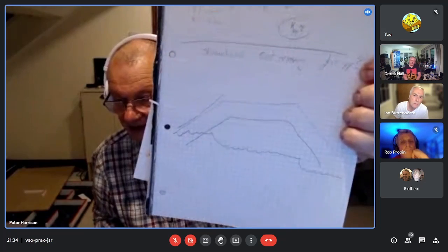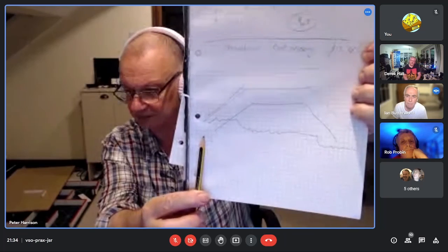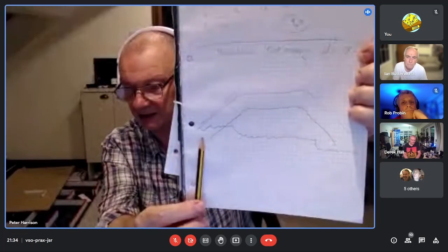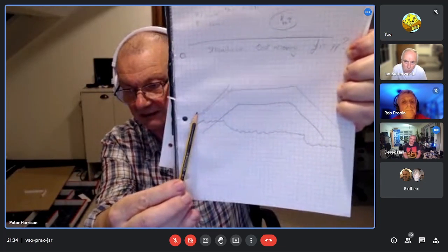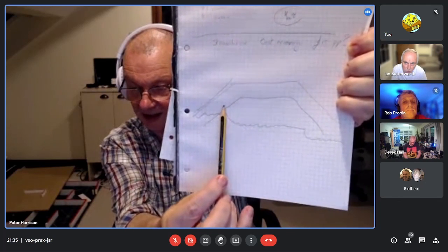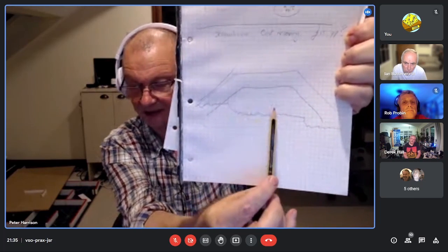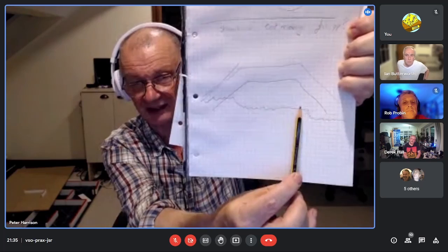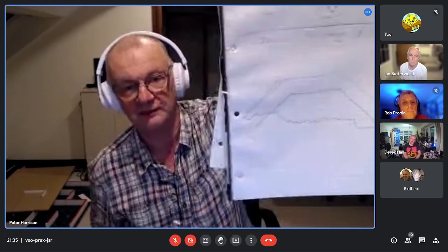Okay, so at the start, I don't know, is that the start on your screen? Yeah. Right. So at the start, the controller will try to compensate for the lack of acceleration by providing a step. And then, going back to front here, once it doesn't have to accelerate, that step will go away and you'll get 0 output because the feed forward is sorting things out. And then when it tries to brake, the controller will provide that braking torque. So it'll all still work, but now the controller is filling in the acceleration portion.